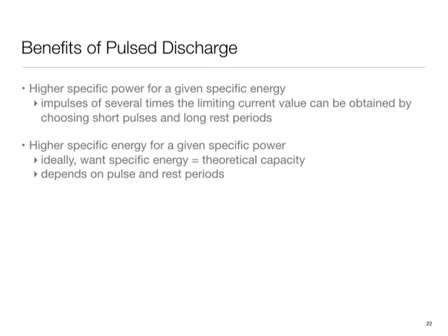How typically would you see non-lithium ion battery chemistries? You see it currently in things like drones and cars, racing cars, and some consumer products where there is higher discharge. NiCads do excel in providing a lot of power for high power usage, so that's why you still see NiCads in those applications. And the other thing is the safety issues surrounding lithium ion.